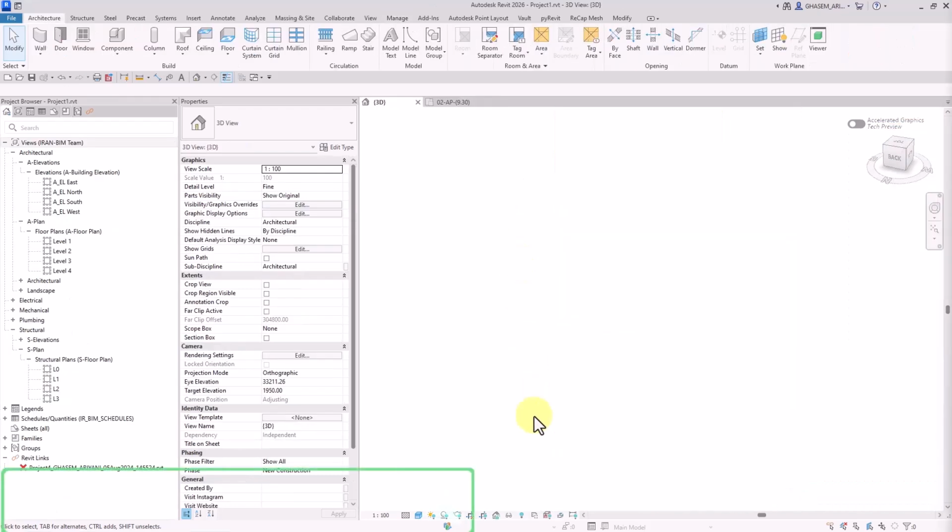In Revit 2026, guys, there's an item which is quite simple, but, well, extremely useful, more precisely for those of you who want to work with Toposolids, floors, roofs, and so on. And basically, if you need shape editing. Guys, when we use shape editing, it doesn't really matter for what. The purpose is not important here for now. When we use shape editing, we would be able to get a copy of the settings and modifications that we would apply in order to paste them on another element. Let me try giving you an example here.